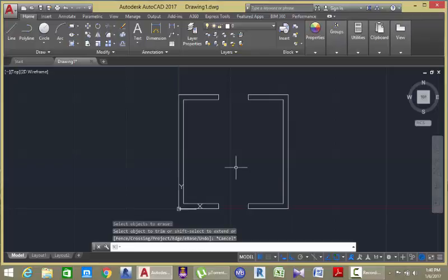In the previous step, I used two methods to draw the short line. The first method is the midpoint object snap, and the second method is mid between 2 points. I hope by now you start to ask questions. Why am I using mid between 2 points, which needs another object snap to complete it, instead of using the midpoint, which needs only one object snap to complete? The reason is simple. Now, let me draw two lines.